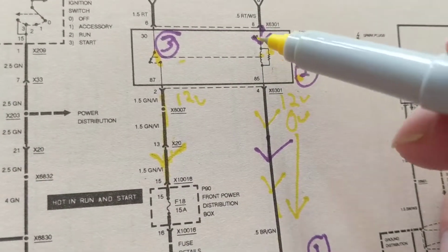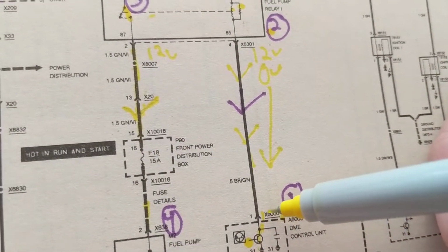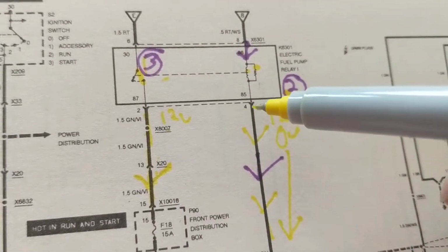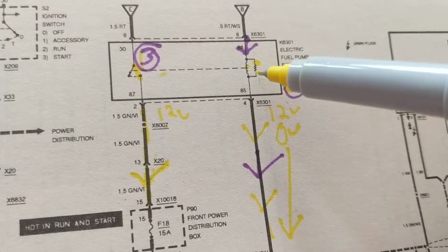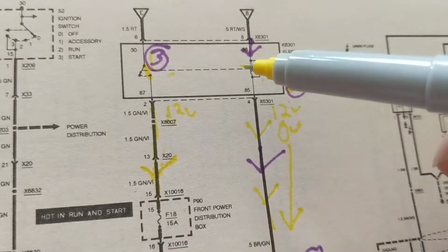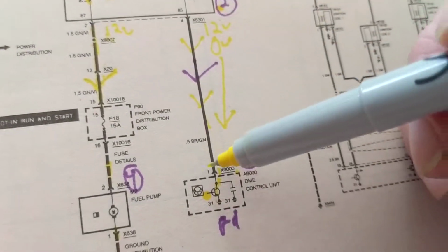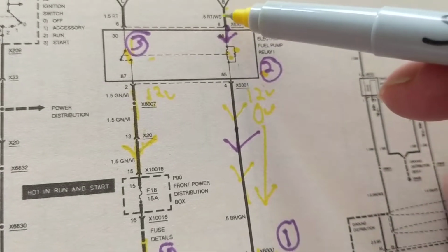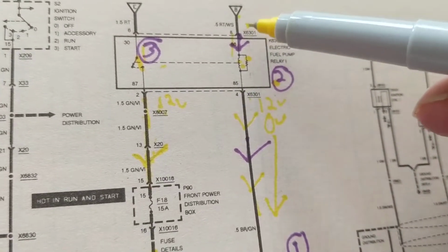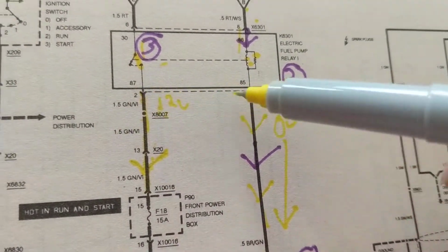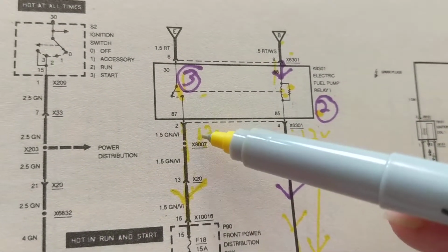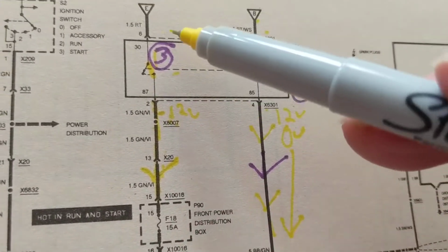Again, when this is operating, this will be grounded. Therefore, this will be now connected to the battery at 12 volts. So again, for troubleshooting, I want to know where to put my voltmeter probe. I always say, go over here. If I have 12 volts over here, guess what? That means this is working. That means this gave me a ground, because current is flowing here. Automatic. I don't have to go 12 volts here. I don't have to go 12 volts here. Once I go to this point, pin 2 of this, then I know that 12 volts over here tells me, hey, this is working.